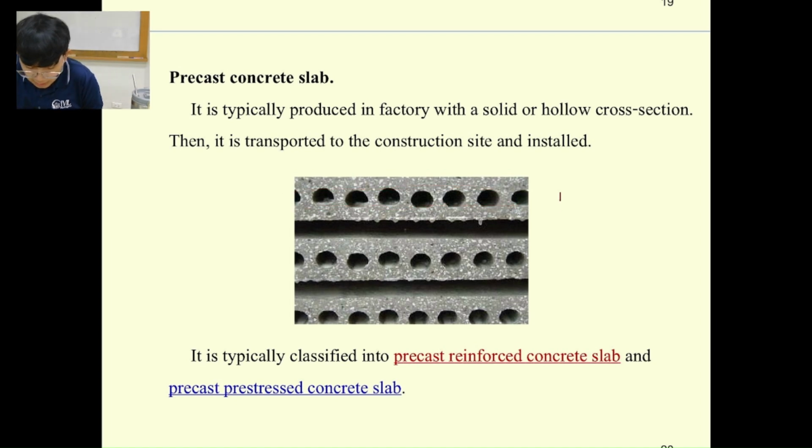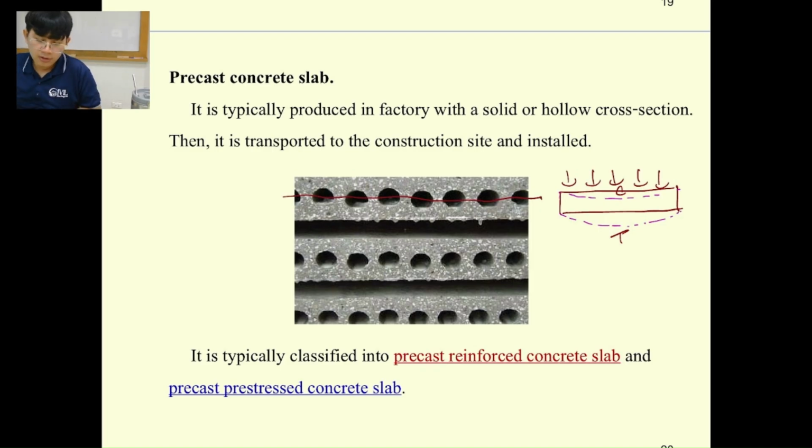Because if you remember from mechanics of material, if you have a beam like this and then you put forces like this, the material is going to be bent like this, which means on top is going to experience compressive strength, and the bottom is going to experience the tensile strength. But they would like to provide the hole at the middle, because the middle is going to be the neutral axis. Okay, the NA section. When it's in the NA section, there will be no force, no stress that is going to occur at the middle section.